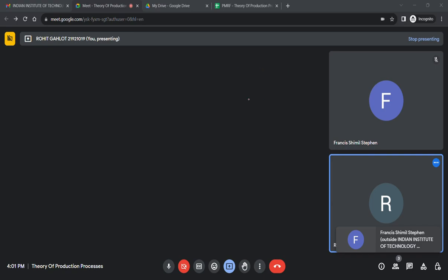As it is a side riser, it will be d by 6. So directly the modulus of the riser is VR by AR, which will be d by 6. Here it is given that the modulus of the riser is 1.2 times the modulus of the casting. So you write the modulus of the riser as 1.2 times the modulus of the casting, and then put the modulus of the riser as d by 6 and the modulus of the casting as VC by AC. Then from this you can calculate the volume and area and find the dia values. So try solving this and tell me what the diameter value will be.